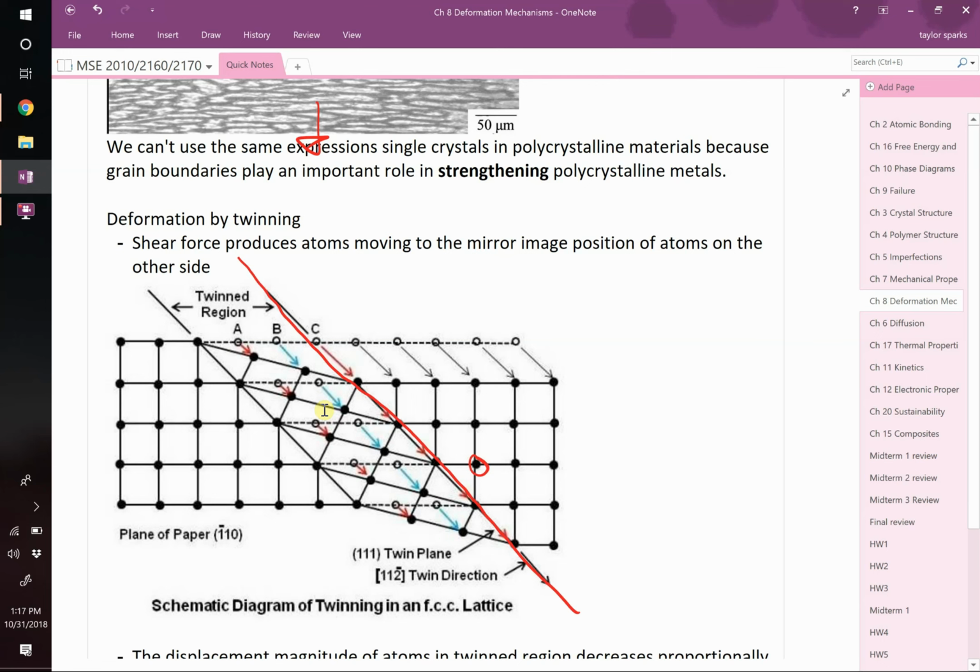On the other hand, when you heat this thing up, the slip systems that were less favorable at room temperature because they cost too much energy to make atoms slide past each other in that tetragonal system, all of a sudden you give it enough thermal energy that those become favorable over moving large numbers of atoms all at the same time. So this is important because this teaches us that when things deform in a material, there's not one way that a certain material will deform. It's not that it's either slip or twinning. It depends on the environmental conditions like temperature.